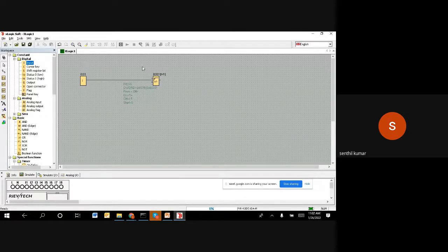You can simply connect the output to the input. When you produce more than 5 bottles, obviously the output is going to become on. When the output becomes on, you take that and give it to the reset. So it immediately resets. Once it resets, the count will go to 0 and then the output will become off.